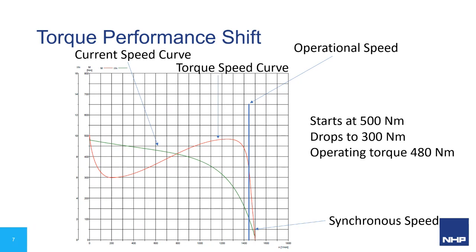The characteristic of a high efficiency motor may cause it to stall during run-up, depending upon the load acceleration torque requirement at certain speeds, and it's all dependent upon what type of load these motors are pushing. Fans are of particular concern in this area, as are loads that may be called to stop under emergency conditions and asked to start fully loaded. These applications, fairly common, include conveyors, crushers, mixers, and other process machinery.